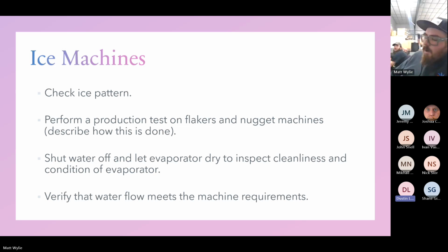Not to go back, but can I go back when you're talking about the cases for a second? I don't know if you guys have ever noticed it. I'm sure most people that have been in supermarkets or convenience stores have, the self-contained coolers at a gas station or a Smith's or something, where Matt was talking about honeycombs earlier. But a lot of these case manufacturers, not only do they have the honeycomb, but they put a baffle in the back of the case. I've seen it in the back, behind the back wall down at the bottom. I've seen it in the back behind the honeycomb.